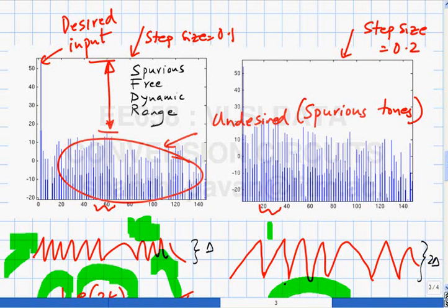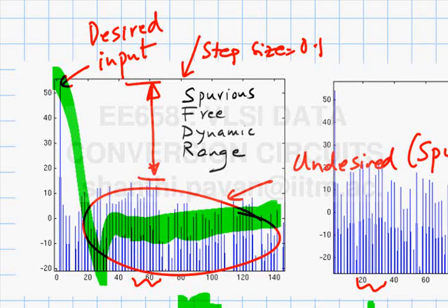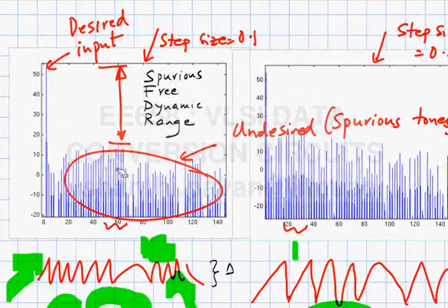So what is commonly done is you digitize the entire band, maybe consisting of 16 or 20 channels, and do the channel selection, which is picking out the particular channel in that full GSM spectrum, in the digital domain, where it's very easily possible to build a very sharp digital filter. If you're trying to digitize this signal, something like this, and your A to D converter itself is adding spurs like this, then the spur can easily be mistaken for a channel, and that can degrade the performance of the receiver. So the spurious free dynamic range is often a spec in a communication receiver.